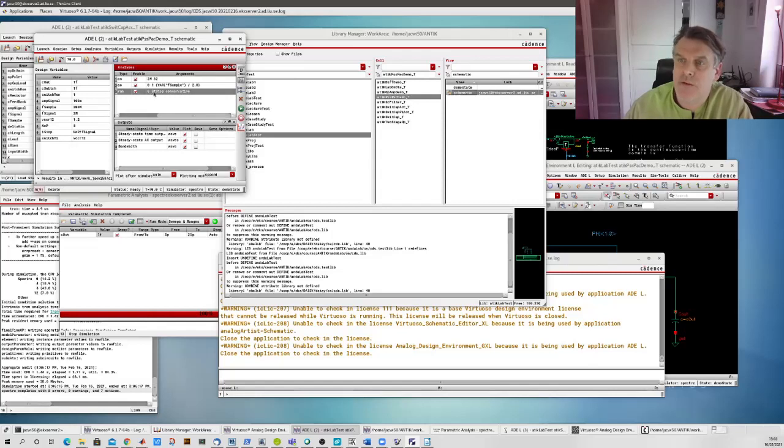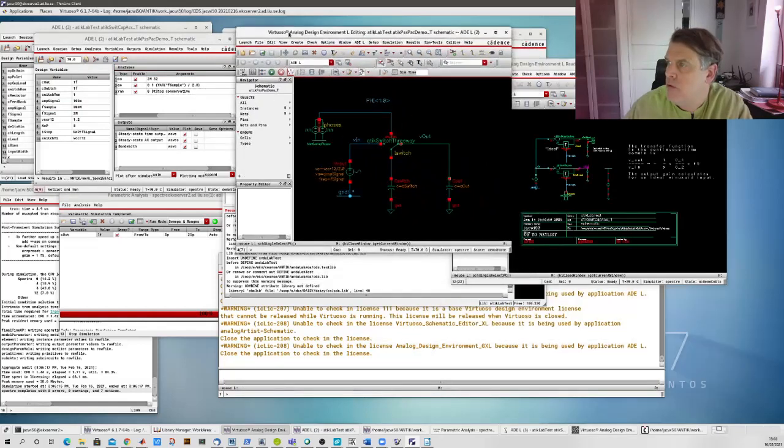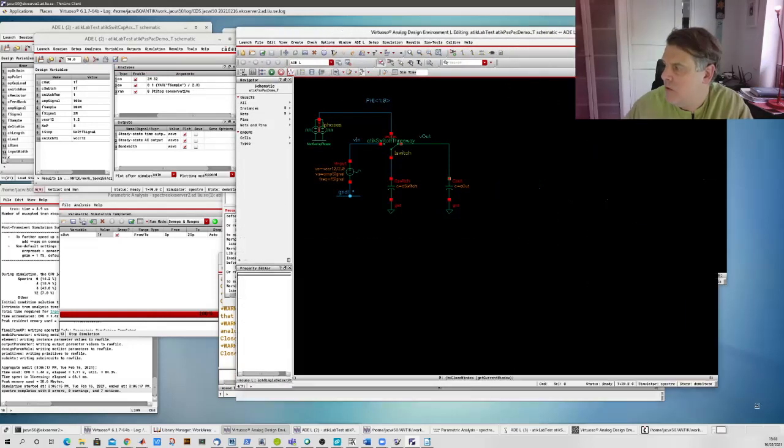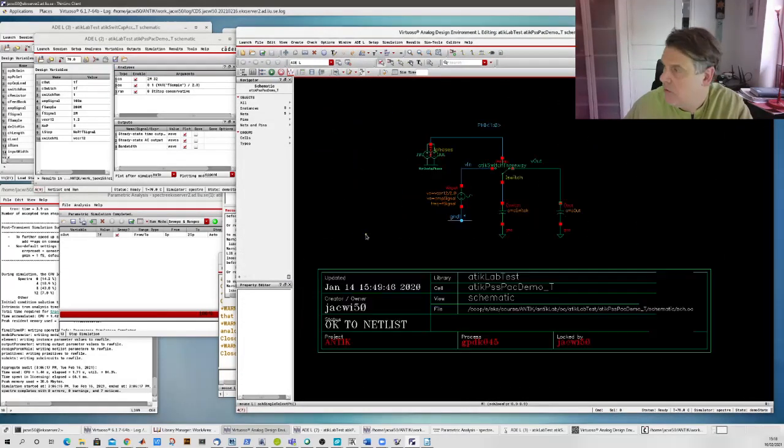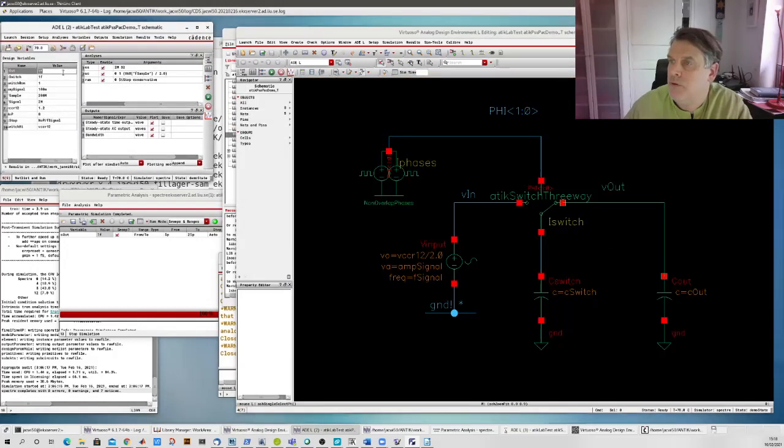And then I've also added a transient here to illustrate these effects. In this particular circuit, we use this low pass filter that we talked about in lecture 3. So I'm going to give this slightly better values, 10 picofarads and 20 picofarads, something like this. I'm going to turn off PSS and PAC at the moment, and then just run the transient.